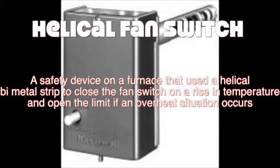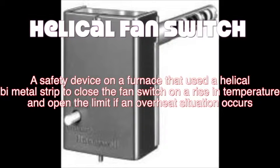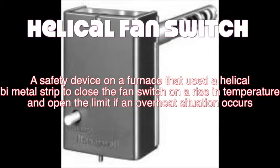Helical fan switch: a safety device on a furnace that uses a helical bimetal strip to close the fan switch on a rise in temperature and open the limit if an overheat situation occurs. That's a helical fan switch.